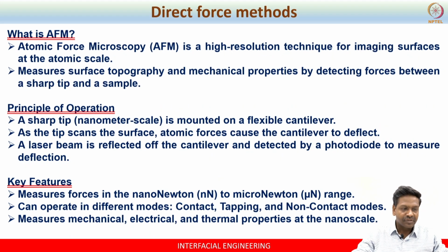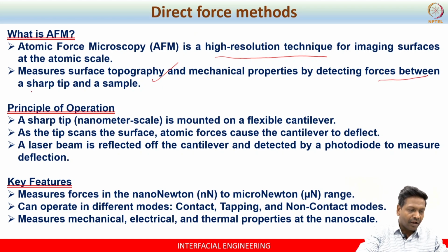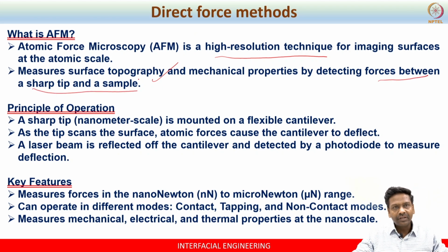Okay. Next comes in this category the AFM, which is nothing but a high resolution technique. Okay. So what it does is it measures the surface topography and mechanical property by detecting the forces between a sharp tip and a sample. So basically, like the previous one, we capture the information about the forces between a sharp tip and a sample.